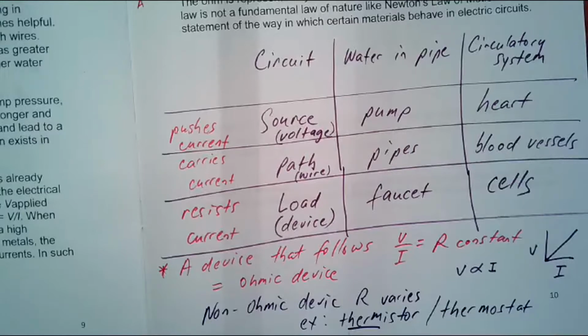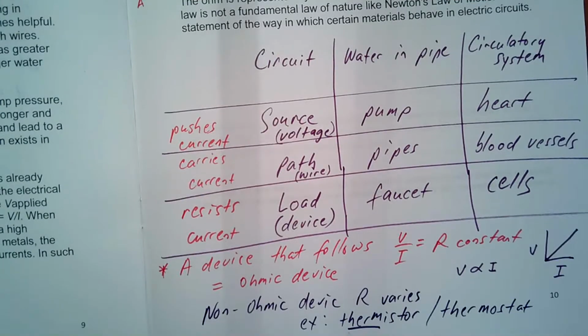So let's say you want your house to be at 20 degrees Celsius, and you open the window or the door and the hot air goes out and the house cools down to say 18. Then the bimetallic strip will react to this change in temperature, and it will bend, and it will then trigger a switch that will turn on your furnace to heat up the room again to whatever temperature you set it as.